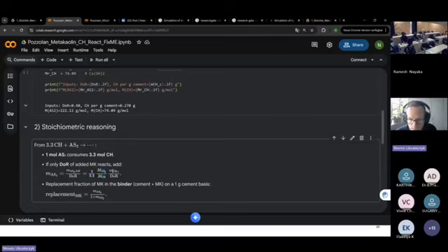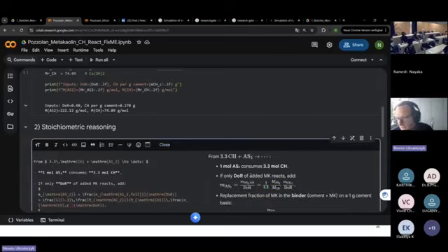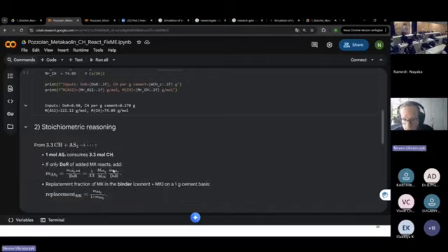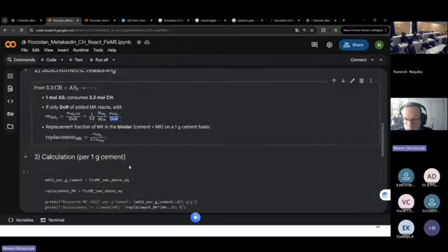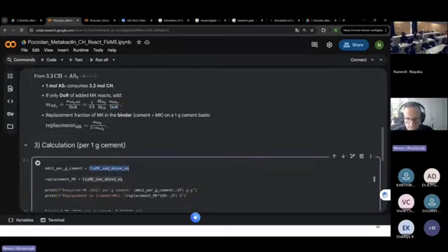And if you multiply by the amount of portlandite in cement, we get the amount of metakaolinite per gram of cement. And then we just divide by degree of reaction, and we get our mass of metakaolinite needed for full reaction if we have a degree of reaction of metakaolinite of 0.4. So now we can again write this equation here. Let's put our molar masses.